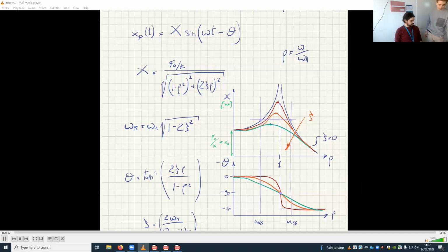So this is minimum. No, that's mean stress. If it's repeated loading, then the mean stress is the same as the amplitude. Then for this one, the formula is this one. If it's Goodman, it's this, yes.